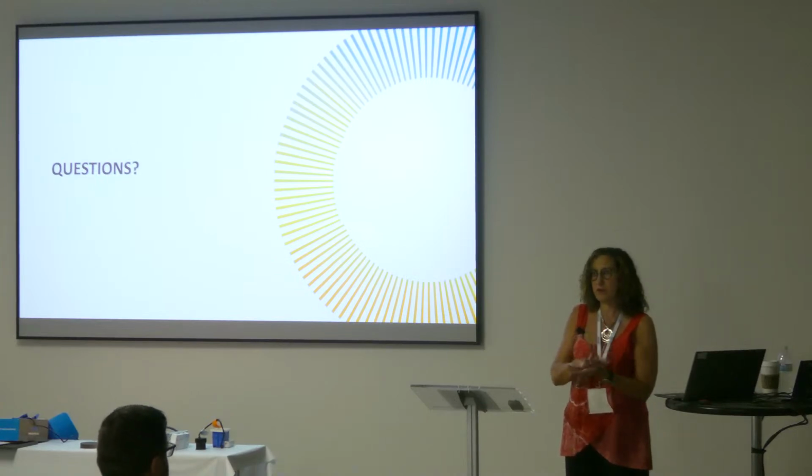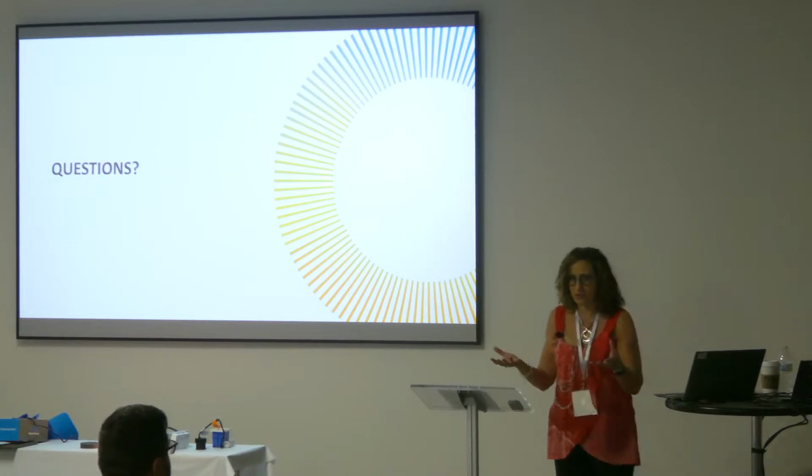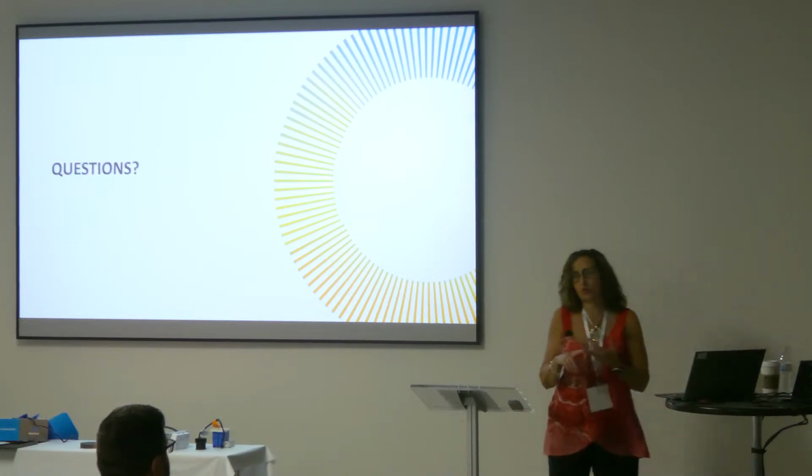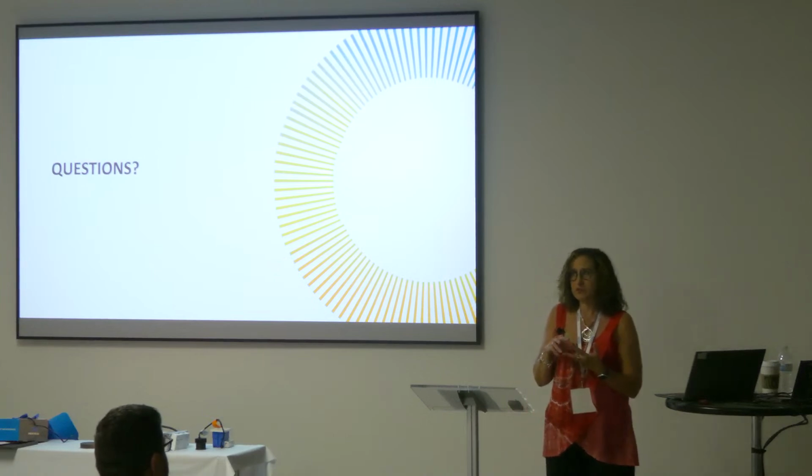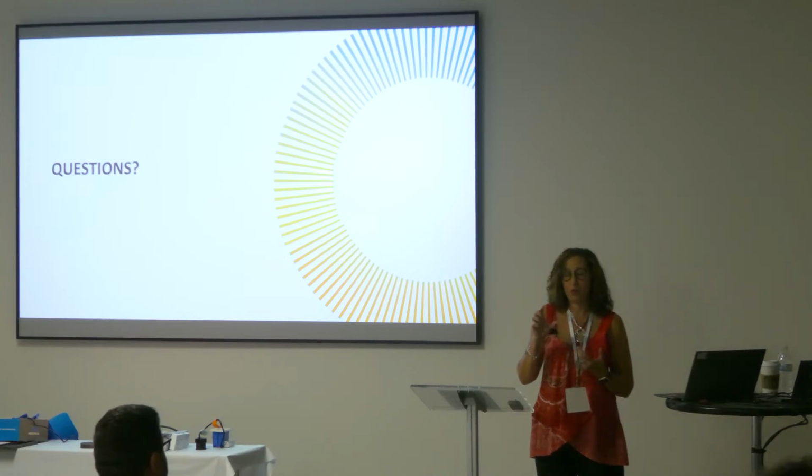When I am really dependent on the contractor to understand, or when it just needs to be super simple for whatever the installation is, I use 0 to 10. I use DMX or DALI specifically when I need to control more than one aspect of the luminaire at a time.